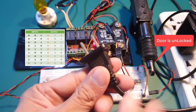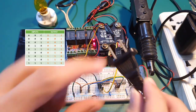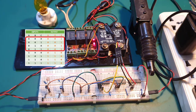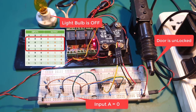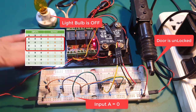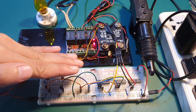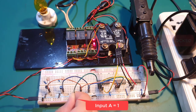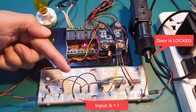Now, I also need to plug this to an outlet. This is for our light bulb. And, same as before, as long as the main switch is at logic 0, the door is unlocked, and the light bulb is turned off regardless of the sensor's value at inputs B and C. But when the main switch A is activated, meaning at logic 1, the door is now locked and the light bulb will only turn on if at least one of the sensors receives dark surroundings.